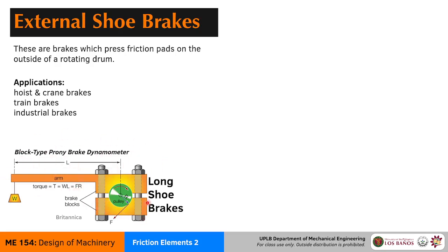It's basically two solid brake pads pressing on this disc, and you can control the amount of torque being exerted by changing the weight that is attached to this arm. So you can hook up an engine or a motor, and then you can apply a fixed amount of torque upon the engine or upon the shaft, and you can check what the speed would be in this case.